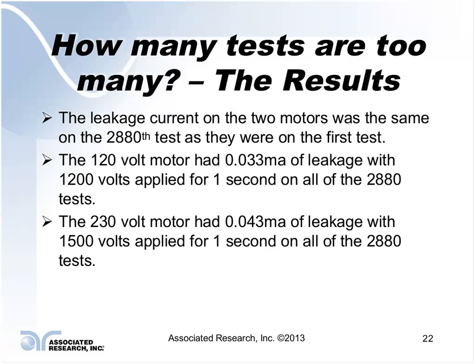To save time, if they got a Hipot failure, they were pulling out all 5 motors and sending them back to the manufacturer rather than determining which motor actually failed. They found it was quicker to let the manufacturer determine which one was bad and which one wasn't. So that was part of the problem.